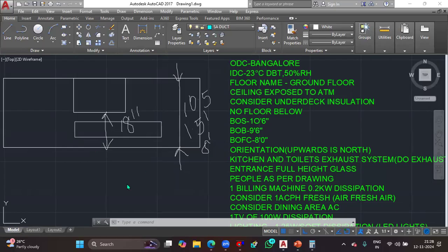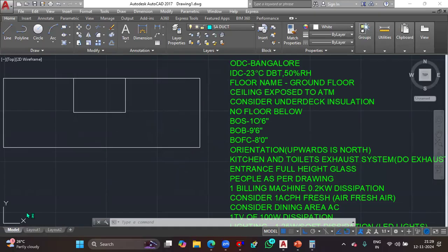And once again, once you finalize your duct height values, you must discuss with your project management consultancy, and similarly with other coordination teams. Then once it's okay and they provide the approval, you can go with the same duct height value itself. So today we learned a lot of things. So is the duct height consideration clear? It's purely providing proper clearance lengths in between those areas itself.